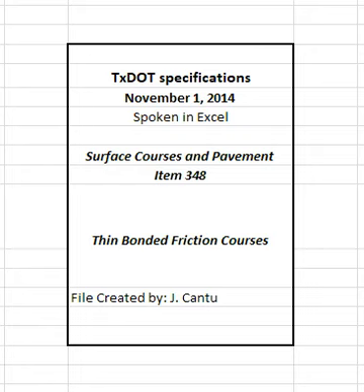4.7.3.3 Screed heaters. Turn off screed heaters to prevent overheating of the mat if the paver stops for more than 5 minutes. The engineer may evaluate the suspect area in accordance with Section 348.4.9.6, Recovered Asphalt Dynamic Shear Rheometer, DSR, if the screed heater remains on for more than 5 minutes while the paver is stopped. 4.8 Compaction.